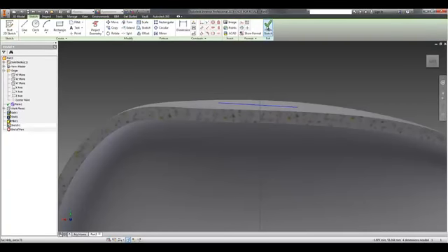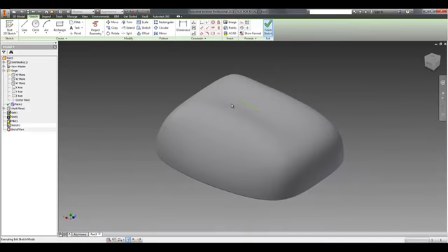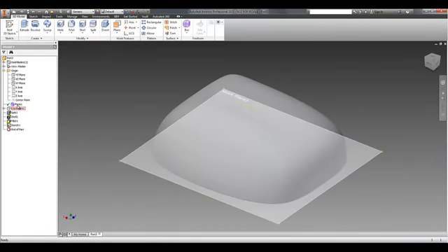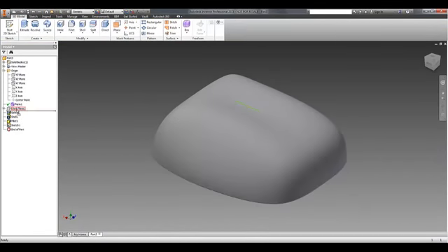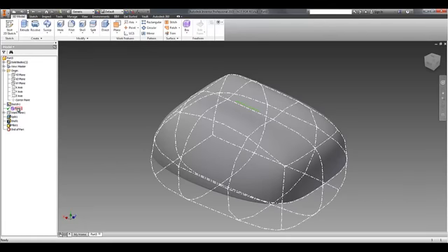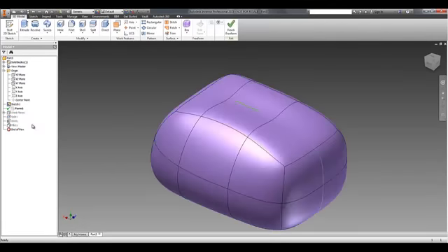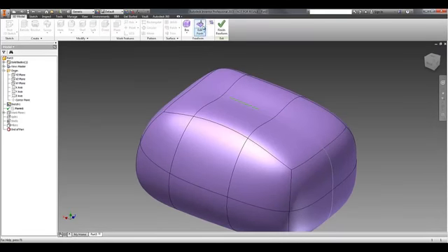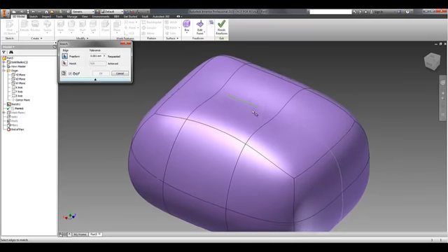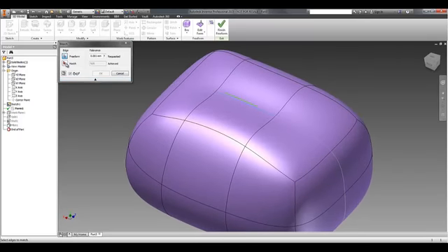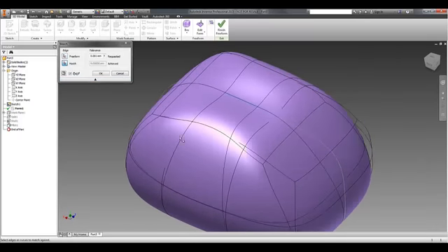So I can dimension that using all the normal techniques, but if I finish that sketch and move the sketch above the form so that it can see it, when I edit that freeform, on the little edit drop down, I can pick match edge, and that'll allow me to select this edge and match it to that.